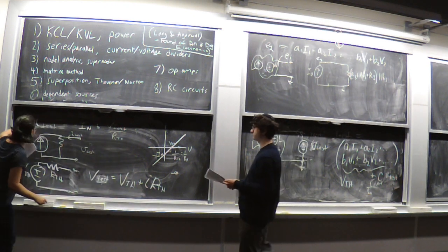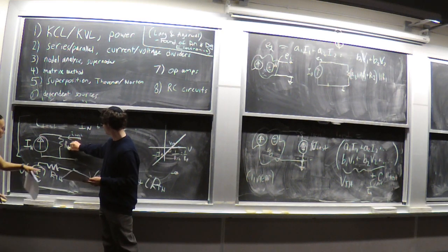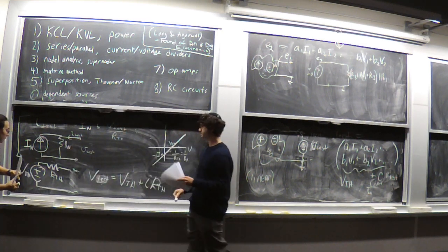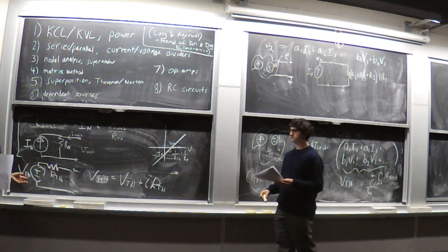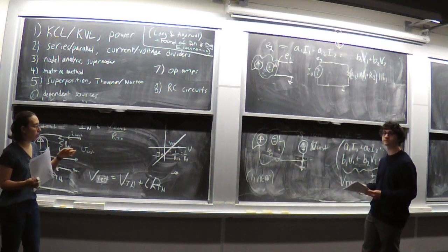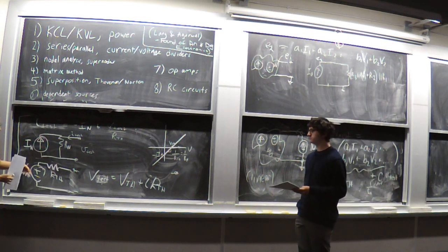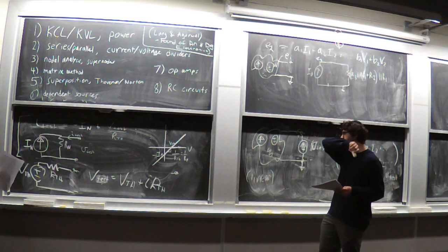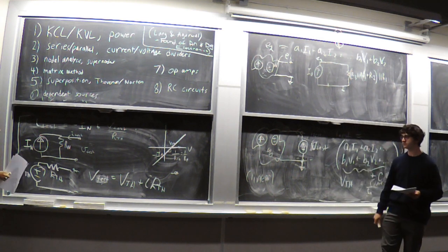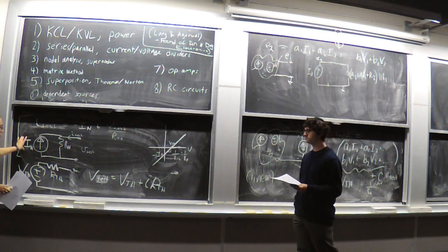So we have our Norton equivalent circuit up here, our Thevenin equivalent circuit over here. The reason this is really useful is now if we want to solve a problem, we don't have to think about everything that's in that blob. We can just replace that part of our circuit from which we've computed the R Thevenin and V Thevenin, or Norton equivalents, and we can just replace it with one of these two models.